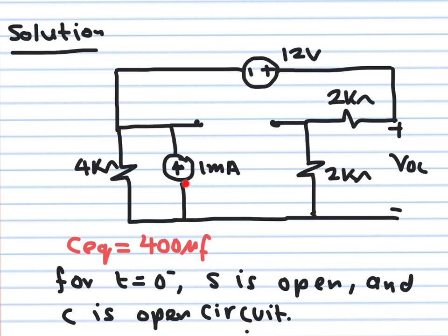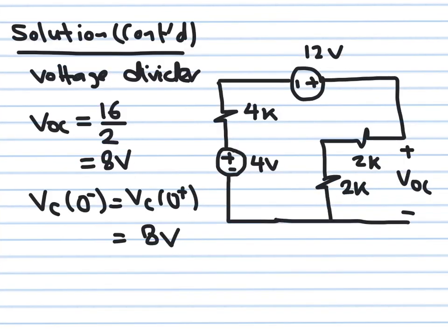So remember, the equivalent voltage will be 1 milliampere times 4k, which is 4 volts, and it's going to be in series with 4 kilo ohm. So this is what I did here. I got rid of this current source and replaced it by 4 volts in series with 4k. The great thing about this is that this is now one loop, okay? And I'm looking for this voltage.